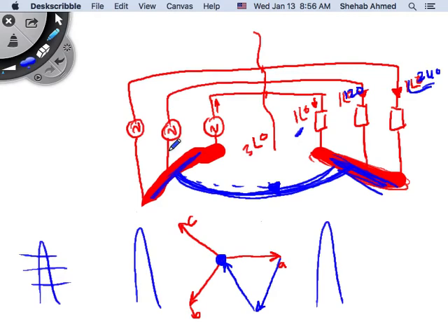So here, in this outlet, you have what? You have one of the phases, the neutral, and the ground, right? You have the neutral. This neutral, theoretically speaking, I should be able to stick my finger in the neutral socket and not get shocked, right? Theoretically speaking, I should be able to do that. If there is an unbalance in the distribution system, and this unbalance is significant, causing significant current and voltage difference between the neutral points of the generator, which is at 0, and the neutral points of the load, which is, because it's a big unbalance, at a certain voltage, you will get electrocuted, right?